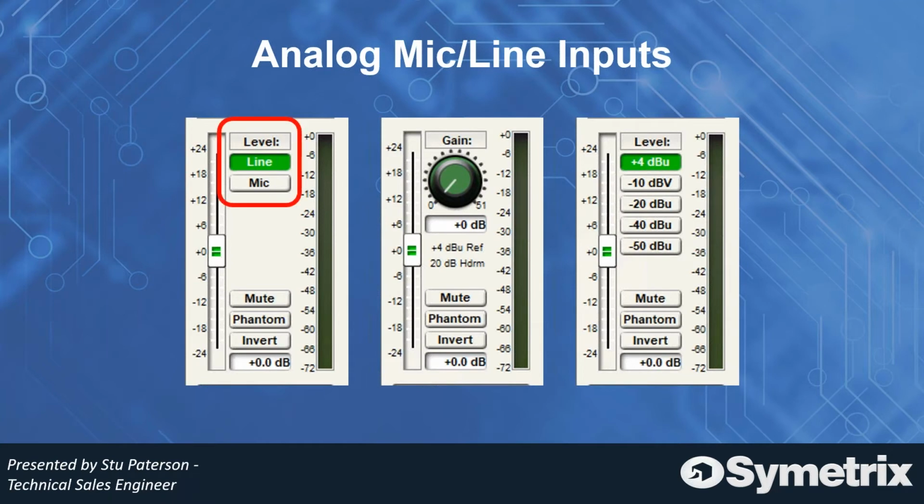So let's go ahead and take a look at that. On the left, we have our fader, but we also have level, mic, and line. So all it's really telling you is this, that we have an input level that's expecting a +4 dBu line level signal if it's set to line, or if the signal is expected to be a microphone, it adds 40 dB of gain.